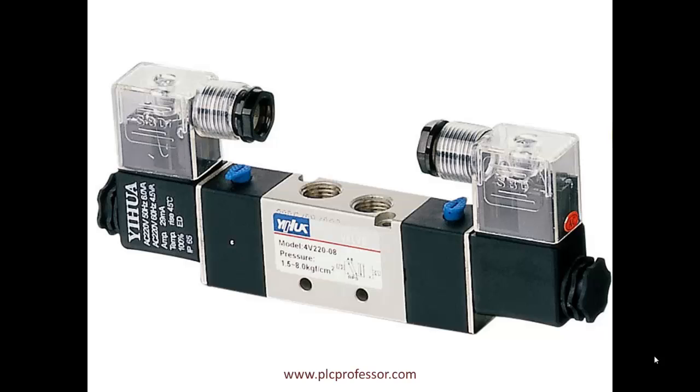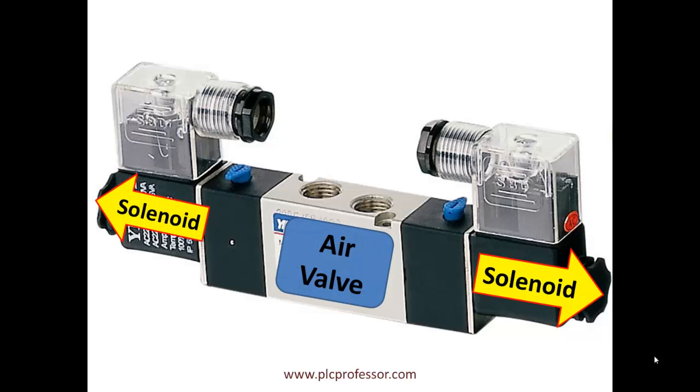Remember that a solenoid is a coil of wire that when we pass electrical current through, and as the free electrons race through the loops of the coil, their individual magnetic fields all join together to produce a powerful magnetic field that can pull a ferromagnetic material such as iron. It is this principle that we operate this valve with. Each coil gives you direction control of the compressed air. So what would the electrical circuit look like to operate this valve? This is where the rubber meets the road, folks. Here we go.